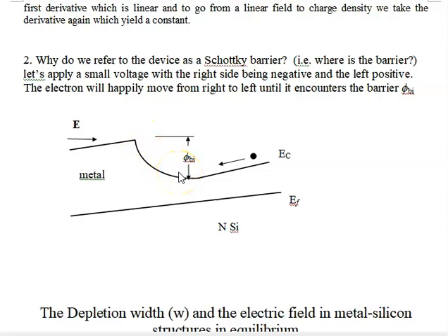And that's why it's called a Schottky barrier. The same thing will happen in PN junctions and in BJTs, bipolar junction transistors. So the barrier comes from the fact that electrons like to go down smoothly, but they come to this point where they see this huge voltage. It's like running into a 10-foot concrete wall, and there's just no way they're going to surmount this.